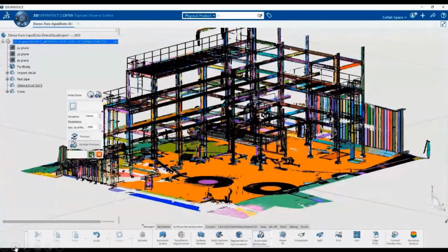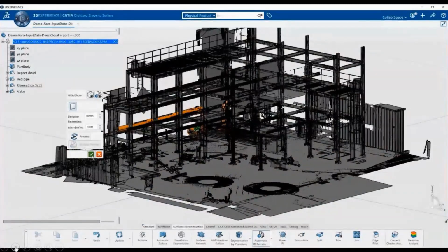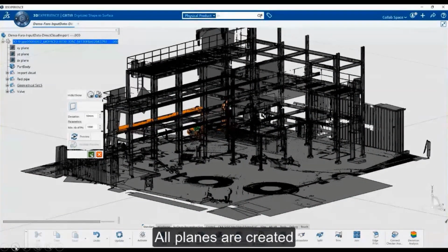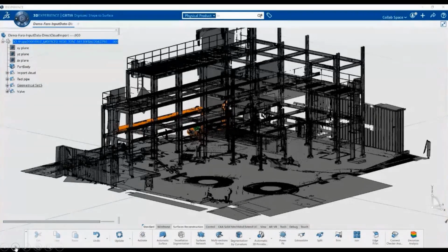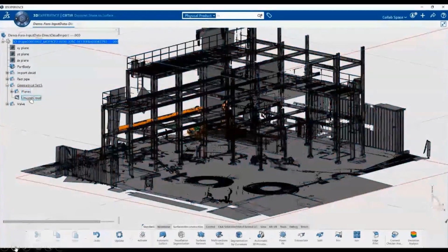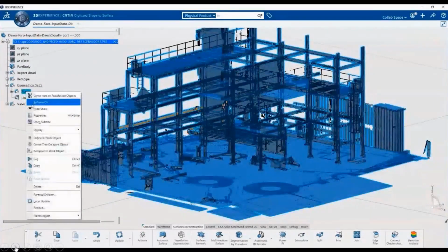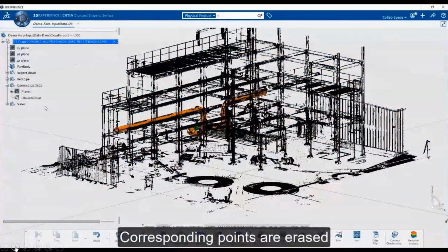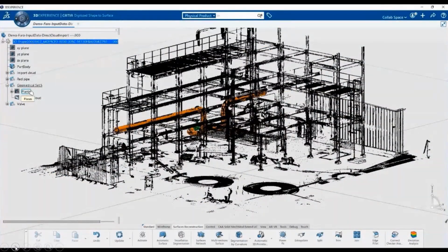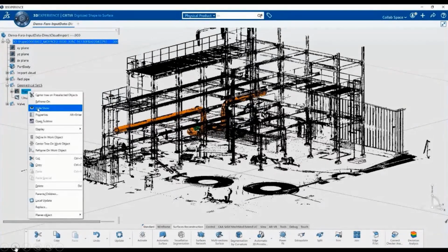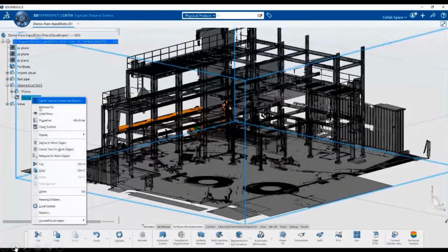and segmentation by color of all the planes as a preview in order to focus on what you want to work on. And then you get a recreation of planes as standard CATIA entities that you can manipulate. Moreover, after that, we are just keeping inside the cloud of points what remains to be done. So we are deactivating all the points that were consumed to create the planes.